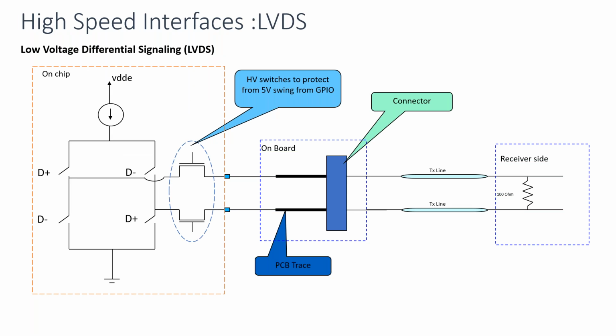So this is an example of a high speed IO. Even though for a user it looks like a digital system, in reality it is an analog system, because of EMI issues, you really don't drive full swing 0 to VDD, at least for high speeds. You have to drive a small signal, and if you want to constrain your system to a small signal, you have to use analog techniques to design those IOs.